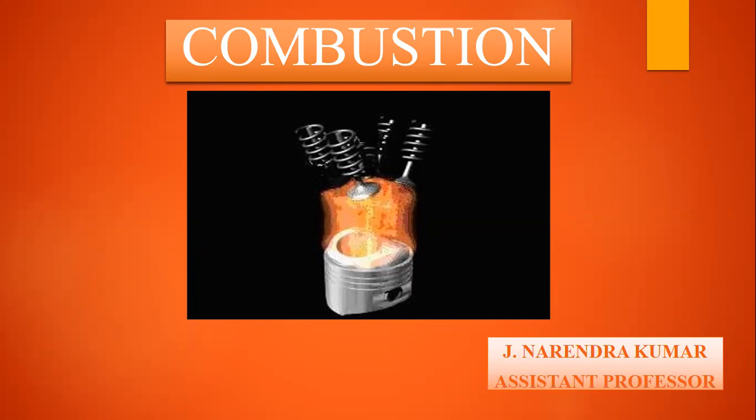and how much fuel-air mixture is going to be there. Is there proper mixing of fuel and air or not? If there is improper mixing, then there will be incomplete combustion. So our main motto is to have higher pressure and temperature. Whatever the maximum possible pressure and temperature is, that much pressure and temperature should be created to have a complete combustion.